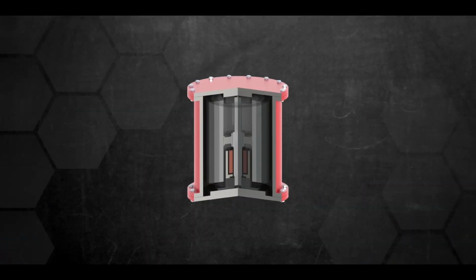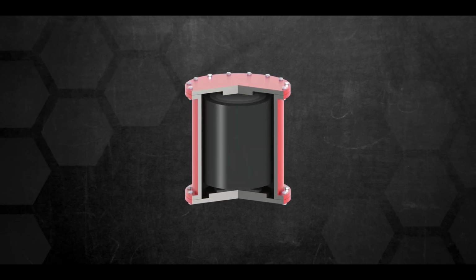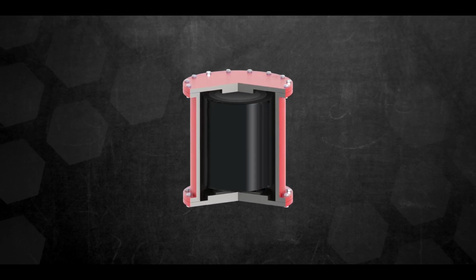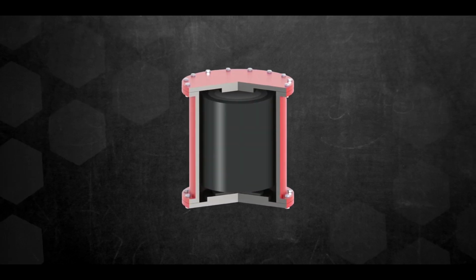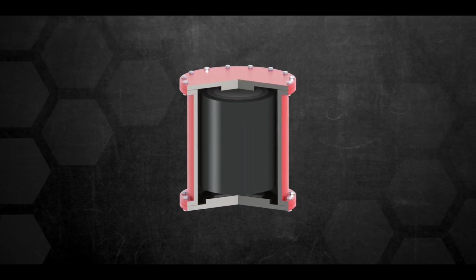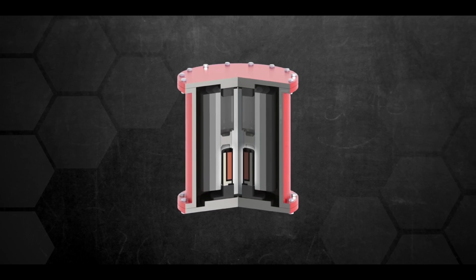A flywheel contains a dual-function electric motor to store and generate energy. It operates like an electric motor in an EV to speed up the flywheel using electricity, so that kinetic energy is stored in the spinning wheel. Then when it's turned off, the dual-function electric motor operates like a generator, and the mechanical energy stored in the rotating mass spins the generator's rotor, producing electricity. It's similar to how regen braking works in an EV, but when it comes down to it, a flywheel can be considered a big mechanical battery.